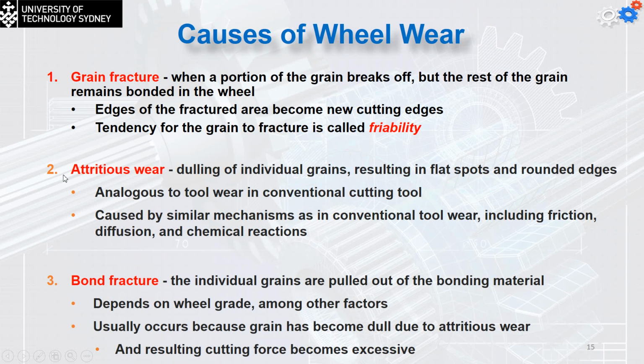We have attritious wear, with dulling of the individual grains, resulting in flat spots and rounded edges. Analogous to tool wear in the conventional cutting tool, and caused by similar mechanisms as in conventional tool wear, including diffusion, and chemical reactions.